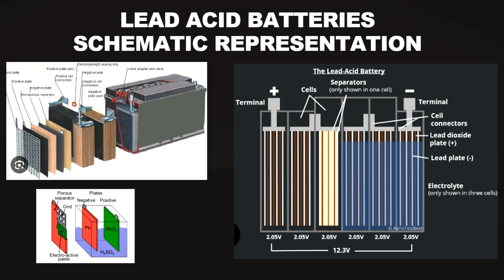Once the separators have been inserted, the group is placed into each of the compartments. The compartments are within the container and there are 5 partitions and 6 compartments in this case. The group is put into each of the compartments and we typically interpartition weld these cells together in a series formation and then remove the terminals at both the ends.